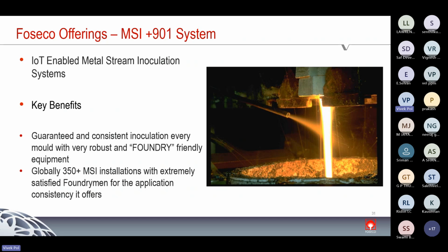The reason behind it, metallurgically, is that we should be mindful about inoculation application. We should always remember that later is better and lesser is better. Later means as late as possible. If we could add inoculant late, then it is effective.